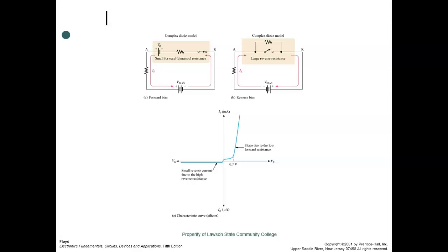So I think the biggest thing we deal with is 12.6 volts RMS. We're going to assume there is no current, but there is. It's so small, but it's limited by current. By the way, the reverse bias leakage current is directly proportional to the temperature.